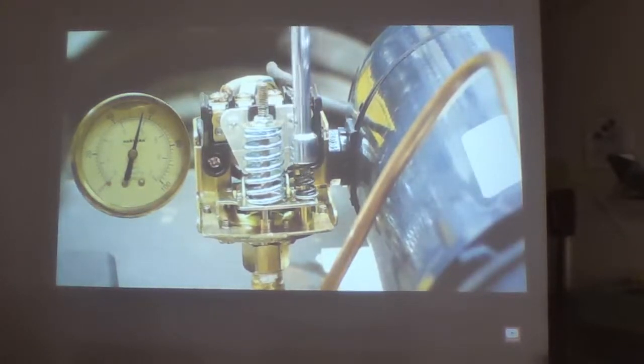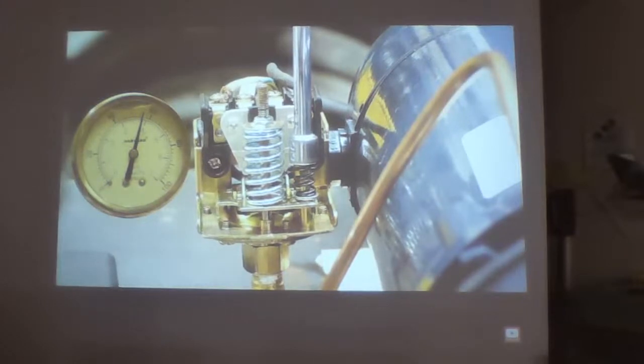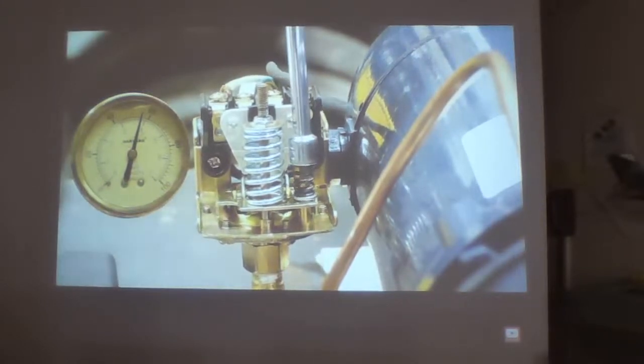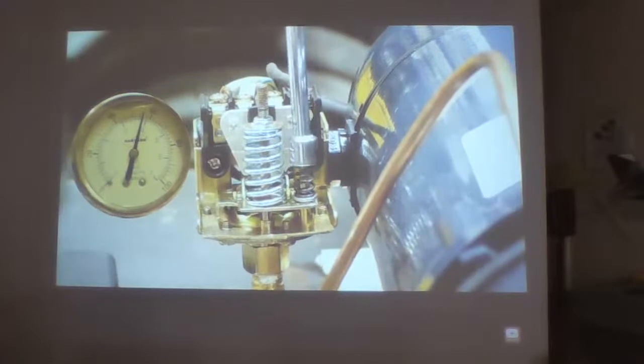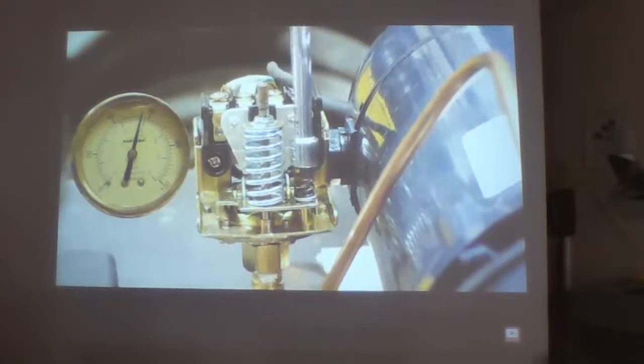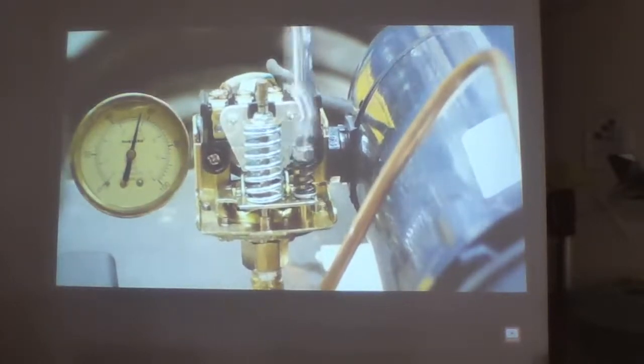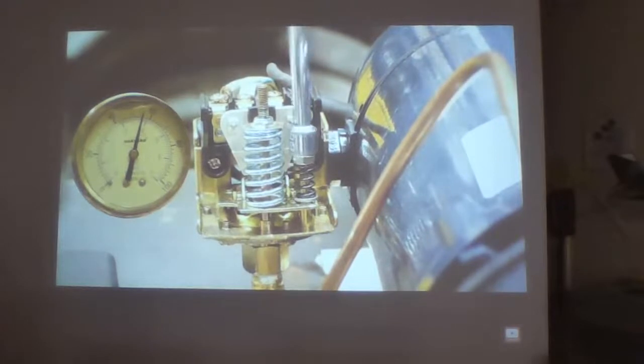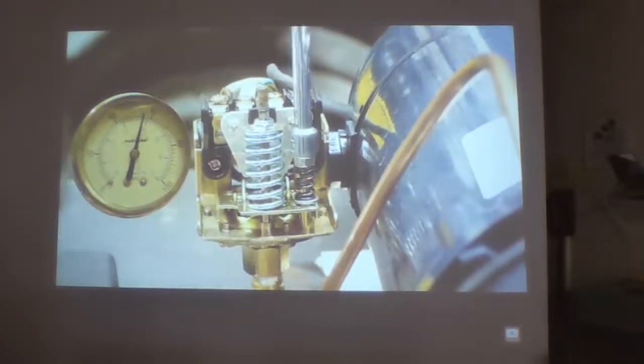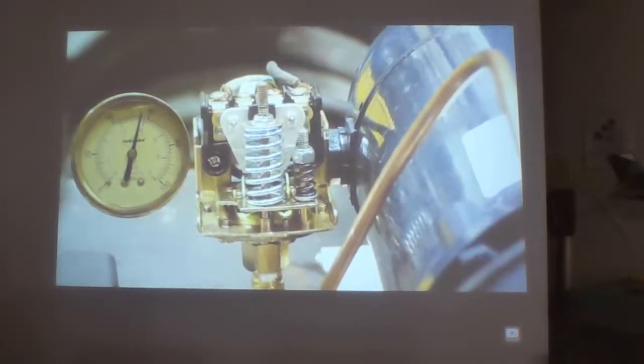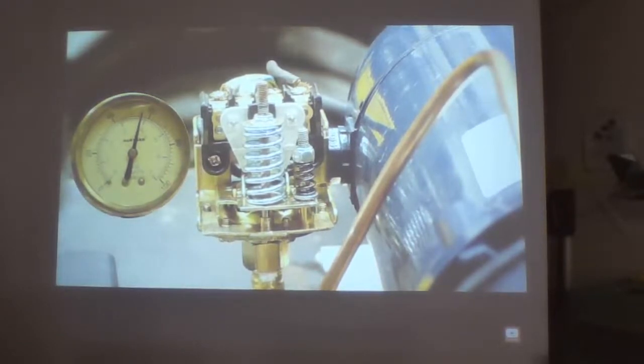We're going to take this one here and we're going to turn it just 3 full turns. 1, or that's a half. 1, 2, 3. What this is going to do is give us actually a longer cycle, so the pump runs longer and also shuts off at higher than 60 PSI. I would guess about 65, 64, somewhere in there, and it's because I turned it clockwise.